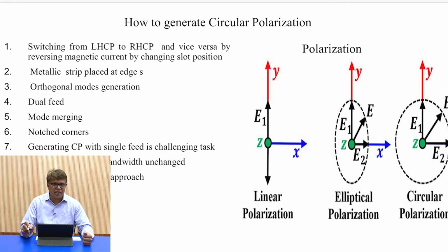It is not exactly the way Lissajous patterns are generated when two orthogonal fields are introduced into the signal, and we get the Lissajous pattern as an exactly circular pattern in a CRO. So, the third case is circular polarization. This is what we require in our dielectric resonator antennas during excitation.